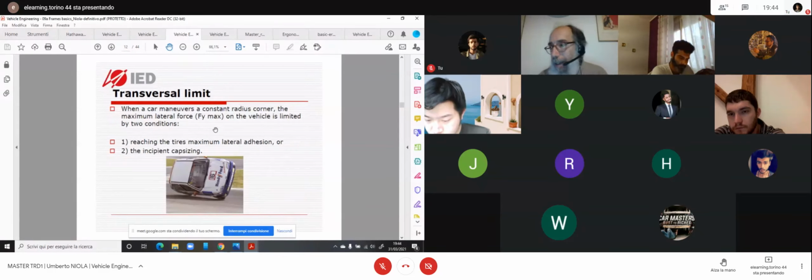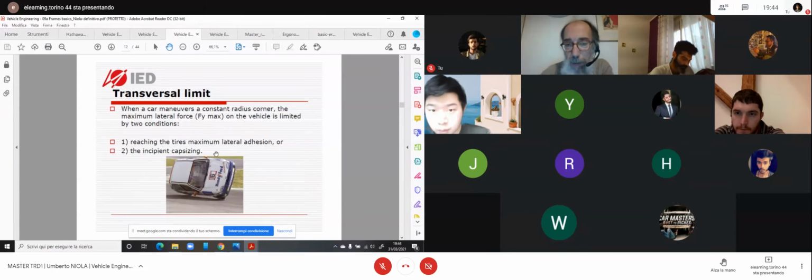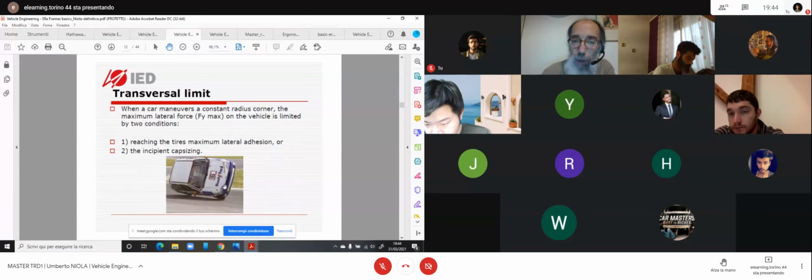Another load you take in consideration when you make calculation is this other one. The complete weight of the car is applied on the side only on 2 external parts. This is different to simply consider the weight of the car simply on the side, because you imagine the contact point is still on the wheels. So you have also the suspension completely differently loaded, and so the transmission of the effort to the mounting point and all the other elements is changing.